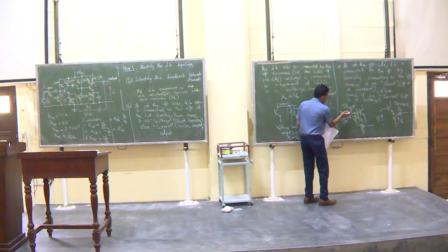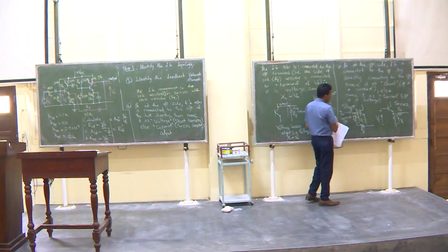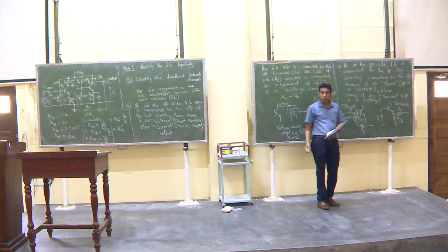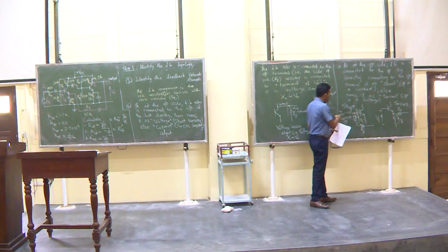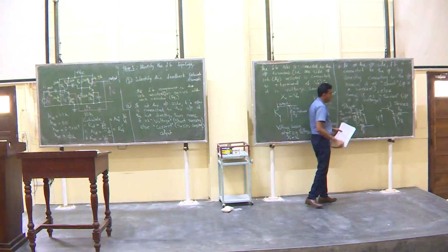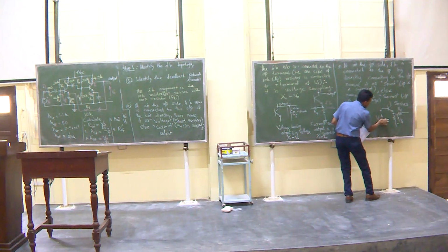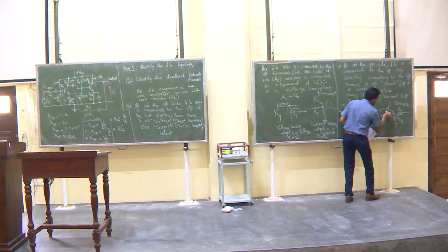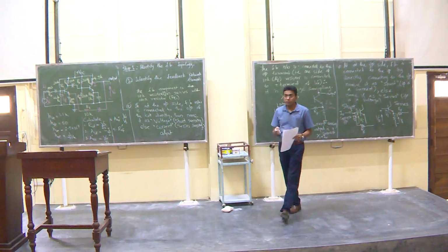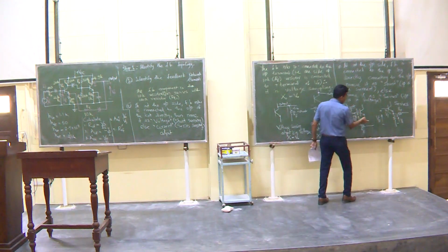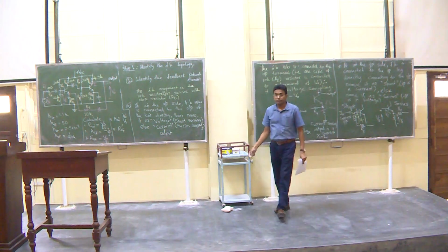This is I s or whatever that comes from here. This is the I in, this is I f. The addition of these two is equal to I s. I in is basically the difference between I s and I f. Here V feedback is this, V input is this, actually this is V s, what will become the V i is that will be your input voltage, okay, because you do not have to have that emitter resistor there for the input, okay.